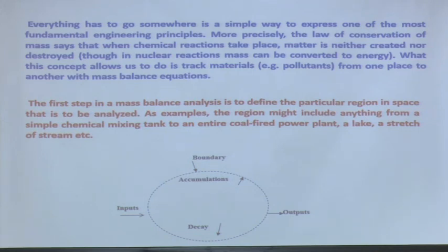What I need to know is the settling velocity of that particle, the flow behavior of my air, what kind of transport mechanism is there. So, how do I know that? I track that particle, how much I have thrown here and what I am collecting 50 kilometers away from there. Then I can say that okay, this is what is happening.